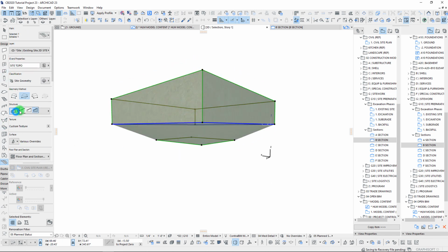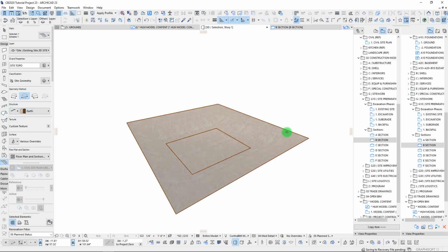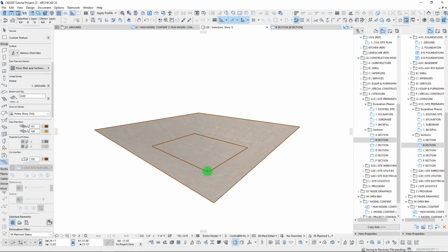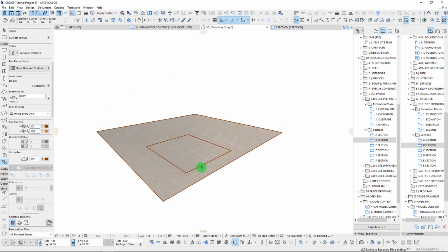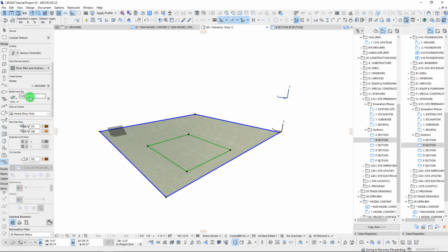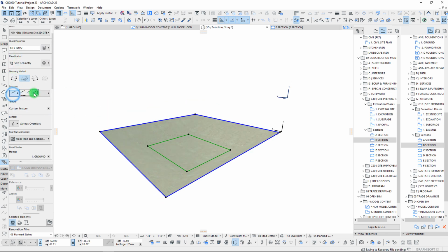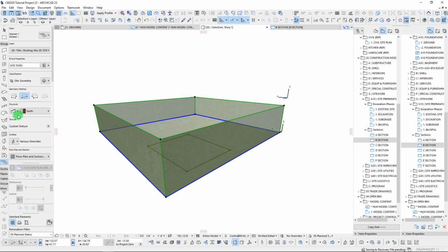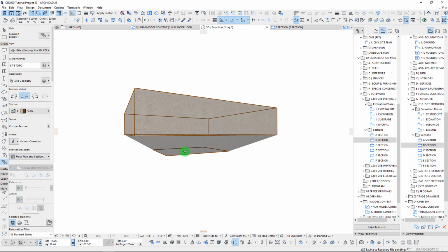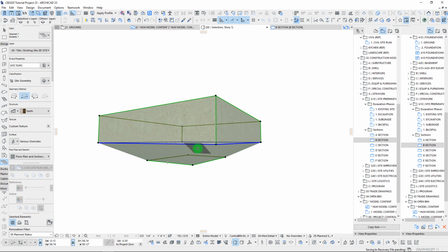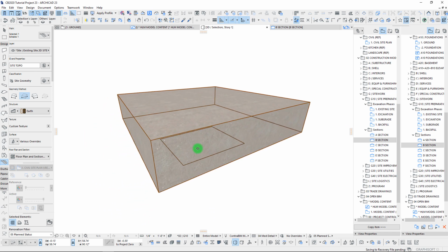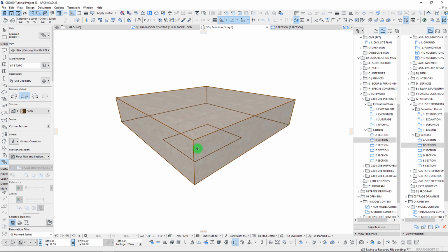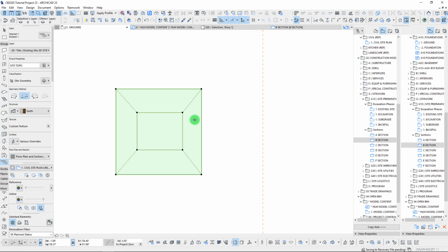And of course we can set this back to a single plane now. It works very similar to what we had before, but now when we go back and adjust the depth on it, it will remember and know that we're moving in the negative direction here. So this is an easy way that we can shape the bottom of the excavation to the depth that we want, and at the same time use this mass as the volume that we will be calculating.